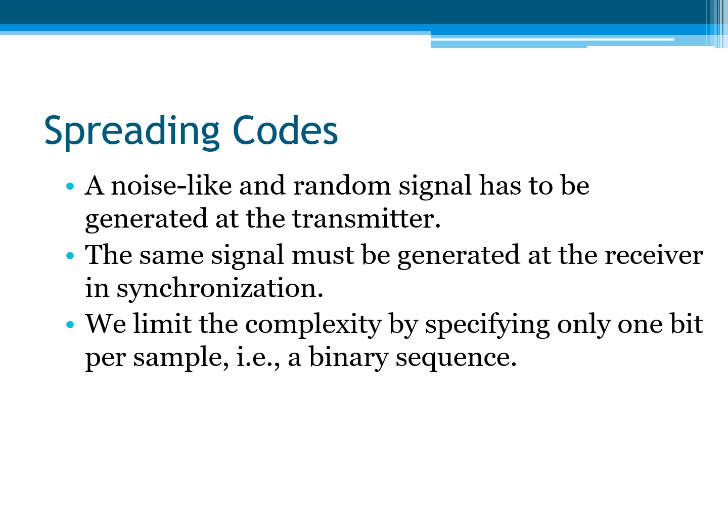Next, we have spreading codes. Spreading codes in the sense a noise-like and random signal has to be generated at the transmitter, and also the same signal must be generated at the receiver in synchronization, and we limit the complexity by specifying only one bit per sample, that is, a binary sequence.